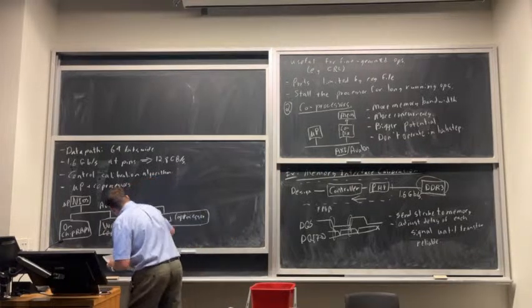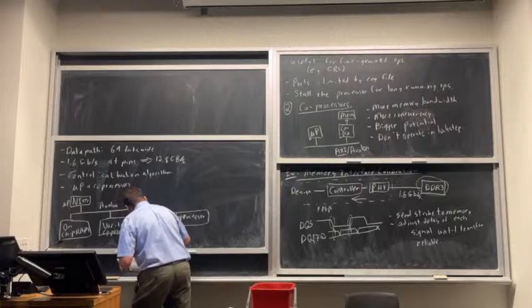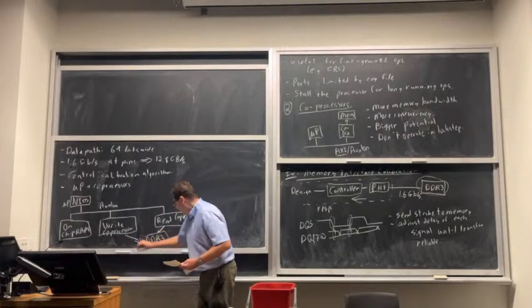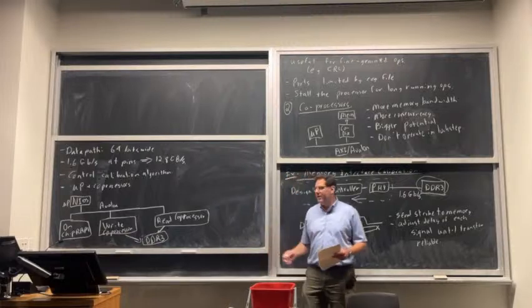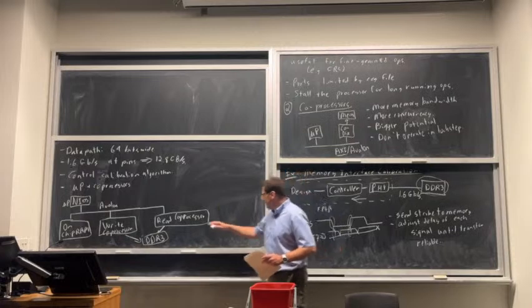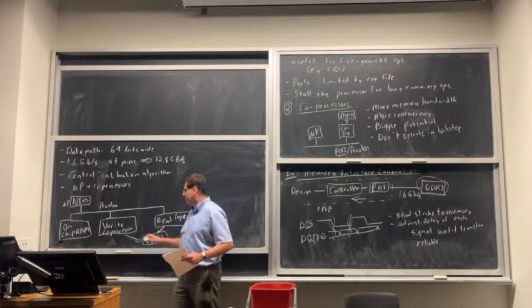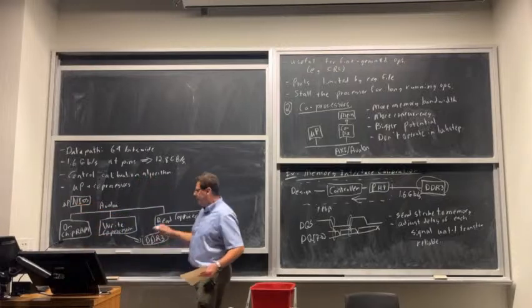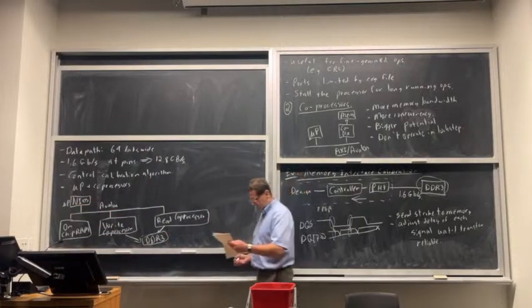Okay, and then these are both connected to the actual DDR3 pins, right? So they can actually directly talk to the off-chip memory, which is important because these two coprocessors can move much more data at a much higher rate than this Nios processor can. So it's not capable of talking to the memory at speed.